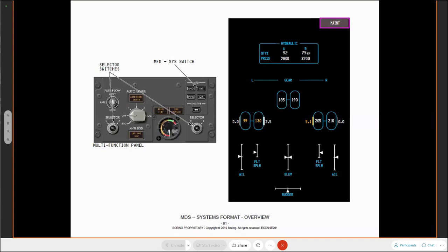It wouldn't necessarily bring on the pressure light on the P5 panel. So long as you've got pressure there, that's fine. The pressure light will be off. You'll just lose the indication on these displays. So this is standard. Every MAX aircraft should have this on it. As I say, if it's available for display, it will be displayed. Brian will go over the quantities and such like with you when he covers hydraulics.